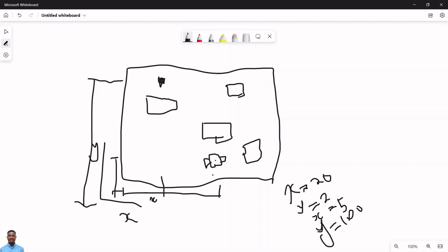So what the algorithm will do is to plan a path, and also the algorithm will ask you where the obstacles are, because there can be two kinds of obstacles in an environment: they are dynamic or they are stationary. When you have stationary obstacles, it will ask you where the stationary obstacles are. However, when the robot is moving, the robot will take care of the dynamic ones, because dynamic ones will be sensed by the robot, and depending on the method you are using to evade dynamic obstacles, maybe it's a wait procedure whereby if there's a dynamic obstacle in your path, wait for it to pass.